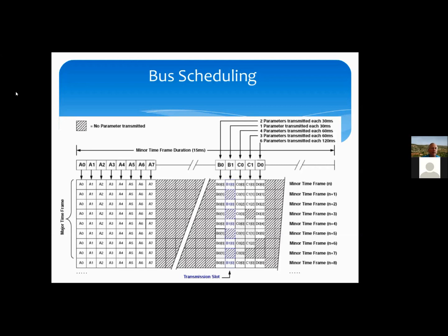The chart is divided into a major frame going down and minor frames going across. These things get sent one line at a time: we're going to send first the first line and then the next line and onward. In this case, I'm looking at the scheduling from the point of view of the engineer of the bus, not from the point of view of a single device, like the engine, but rather all the devices together. Because the architect of the system's job is to make sure that there's enough time for all the data that has to get transmitted.